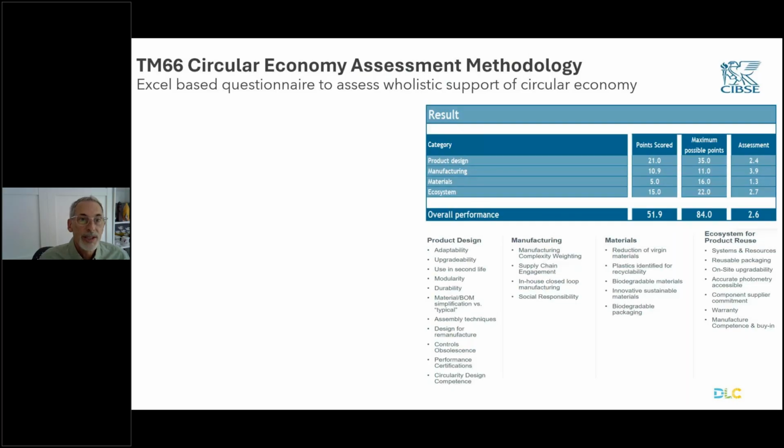So one of the tools that's available is TM66. This is another tool that was developed by the Chartered Institution of Building Service Engineers out of the UK, specifically developed for luminaires. It's an Excel-based questionnaire that helps a manufacturer or a specifier assess how well a luminaire has been designed and manufactured and supported to enable a circular economy.